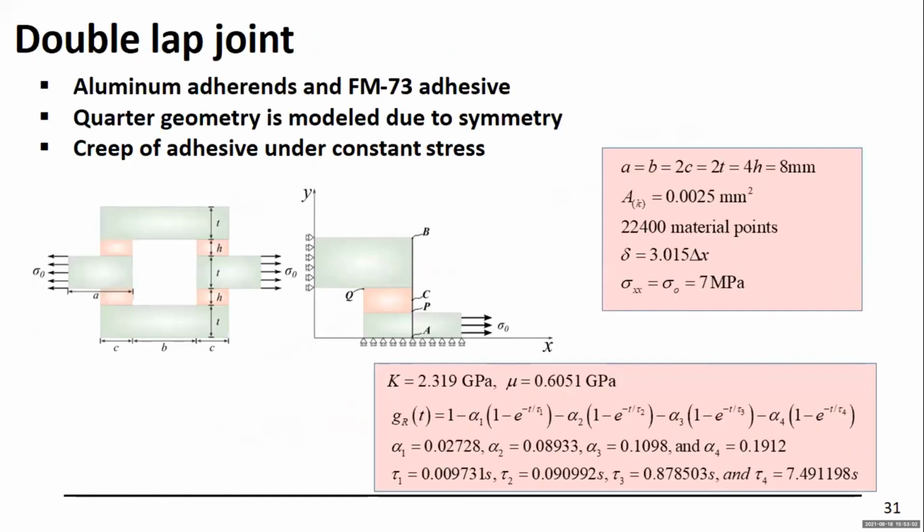Let me go to this previous slide here. As you go from here to here, you're going to have a jump, right? Some sort of discontinuity. We looked at two different ways of doing it. Basically, you can do averaging, or you can approach, for example, Young's modulus as I go from here to here in the form of a sigmoid, right? So it's like a continuous function or hyperbolic tangent, for example. We looked at both of those. So when the modulus goes from here to here, you approximate that variation through a hyperbolic tangent function. So okay. Yeah, I got it. Either way, you can use it. It doesn't make much difference. I got it.